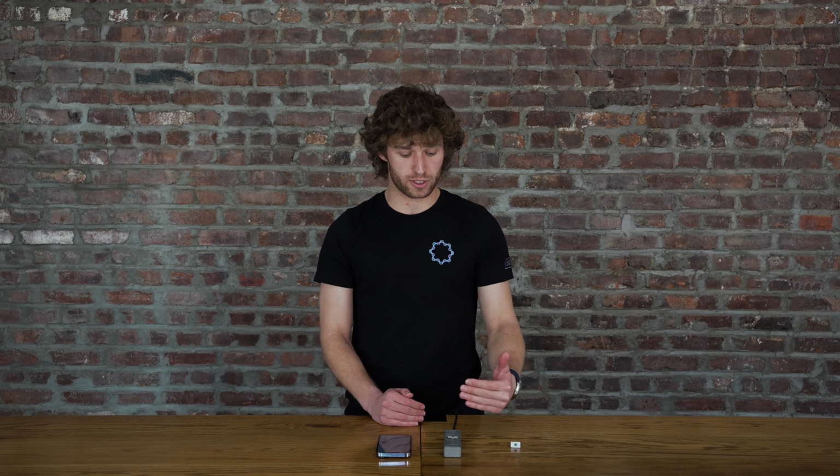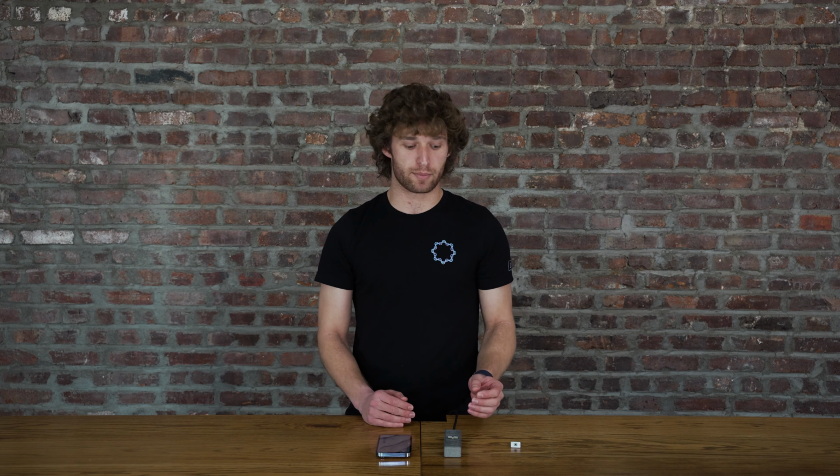During the casting process, you'll be prompted to select which port you want to use as your reset port. Make sure you don't pick a port that's being used by a module in the equation. When you want to reset your device from keyboard mode, you're going to take a button module, put it into the port you choose, and then hold it down for 5 seconds. That will set the device out of keyboard mode, and you'll be able to connect to it again from the app.